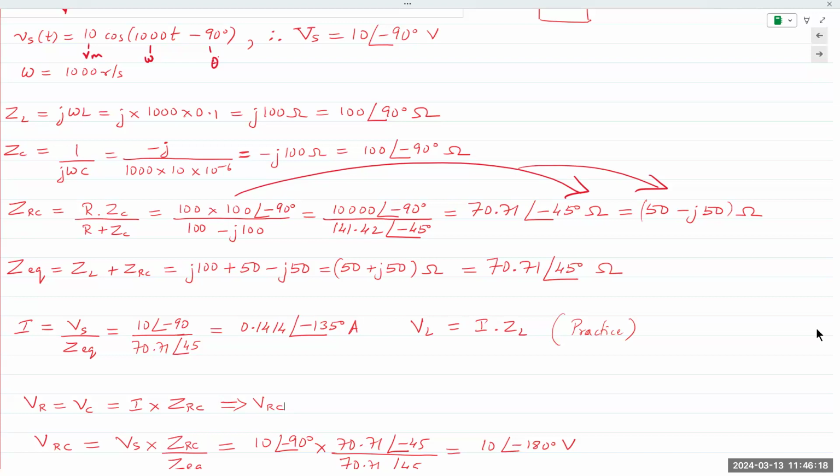It's not RMS. It's still the phasor. We are still in phasor form. We are not yet to the power. Power is average power, and then average power requires RMS values. RMS is just peak value divided by √2. And we will see that when we apply it to the power equation, which is in the next two steps.